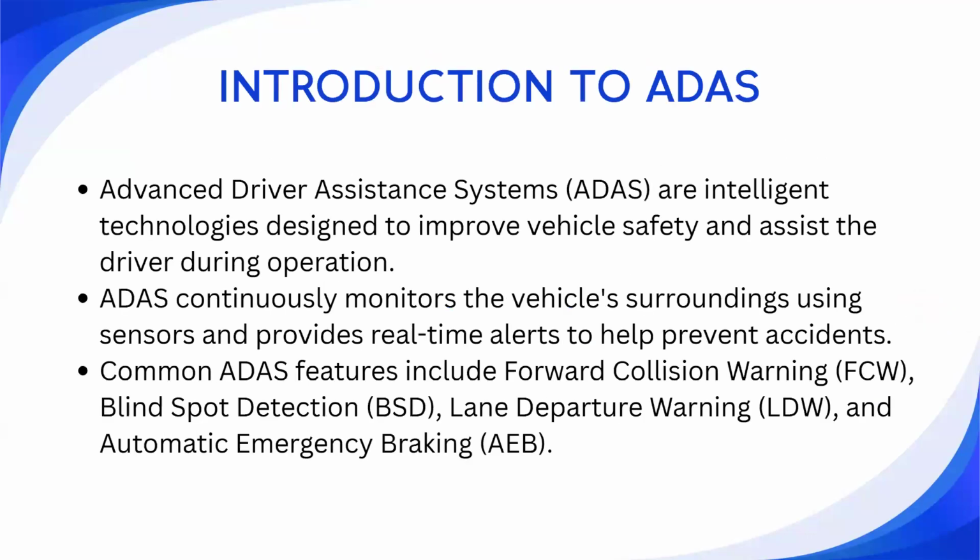Coming to ADAS, which is also known as Advanced Driver Assistance System. This system assists drivers by continuously monitoring the surroundings using various sensors such as ultrasonic sensors, cameras, and radars. The primary goal of ADAS is to reduce accidents caused by human errors. In our project, we implemented forward collision warning and blind spot detection using ultrasonic sensors. Whenever an obstacle enters the defined safety zone, the system immediately alerts the driver through the dashboard.